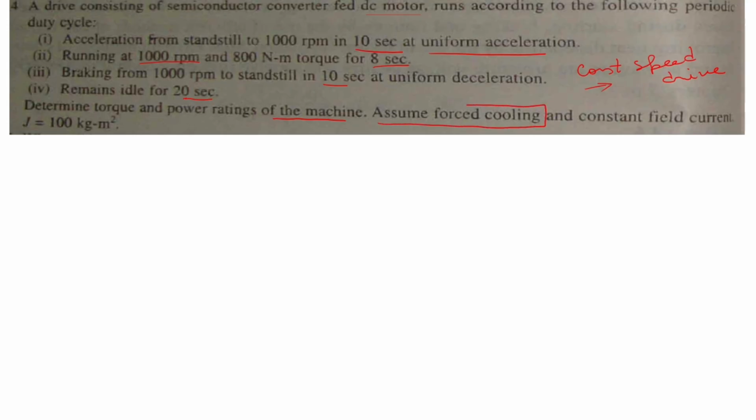This is important, as I have already described in the previous video that whenever force cooling is given, we can use the equivalent torque, power and current method to solve this type of question. Also it is given that the field current is constant. It suggests that the torque is directly proportional to I. I have discussed all this in the previous video. Now we will solve the question step by step.